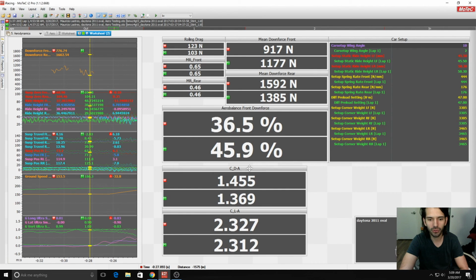The coefficient of drag changed by almost 1/10 of a count of drag. The lift went down a little bit actually, which is not a surprise, since we're talking about downforce, not lift force. You can see it here just in plain numbers where the downforce went.